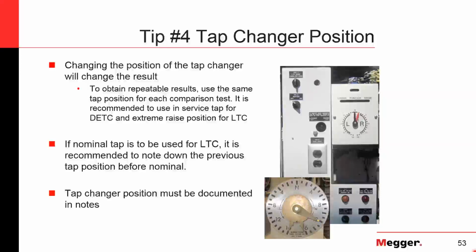And the thing to look for is magnitude shifts or shifts in resonant points or loss of resonance and things like that. One thing that I would like to add to what Robert just commented: if you do your SFRA test and you get a response, like Robert just mentioned, you may have not just one single type of fault on your winding, and there's many other things.